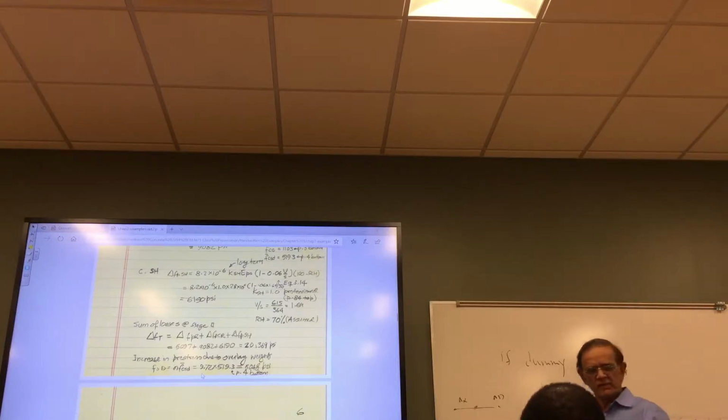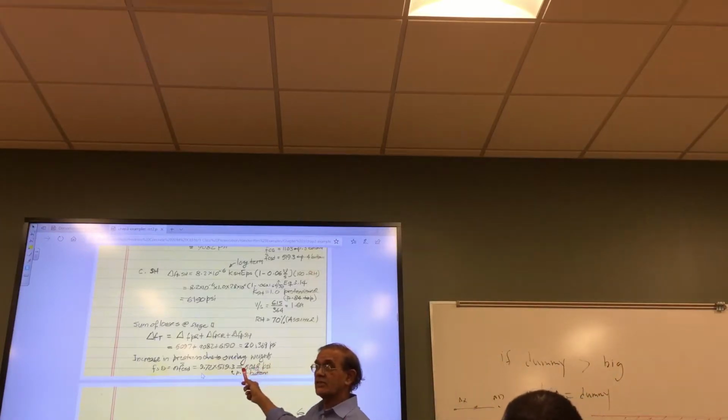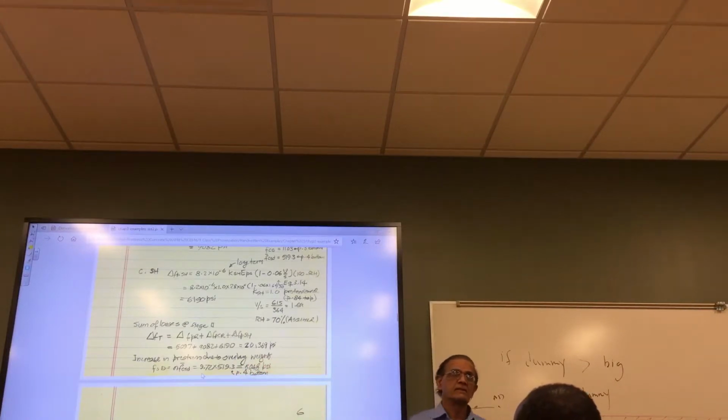So you're trying to stretch the material on the bottom. When you stretch the material by adding the load, it is going to have more tension. Does that make sense? So that's the gain in pre-stress. This is a gain, opposite to loss, so this gain has to be accounted for.